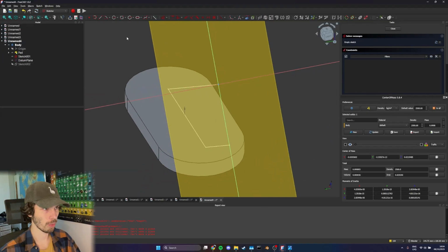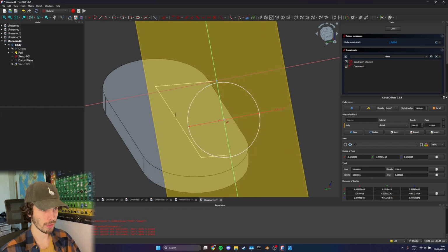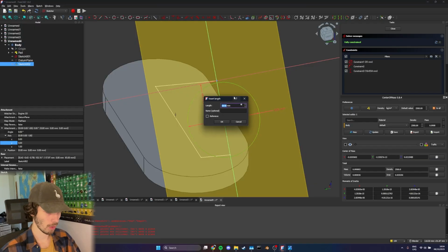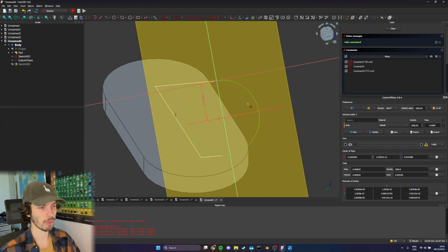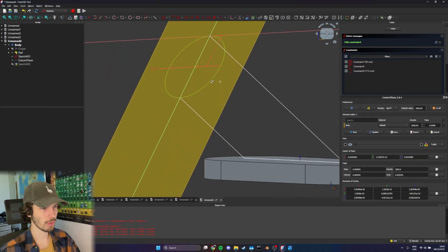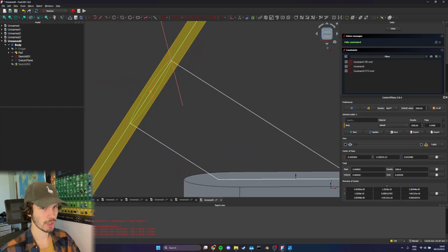Good thing we already have one point, but we'll go in here and create the circle, which is 35 millimeters. 35, and click OK. We have to have it symmetric, so let's click in on the dimension tool. 35 divided by 2, we'll have it perfectly centered over there. So at this point, you should be seeing the circle over here in the air in the specific angle.